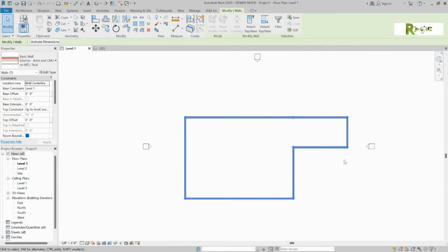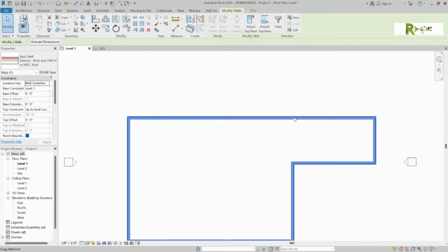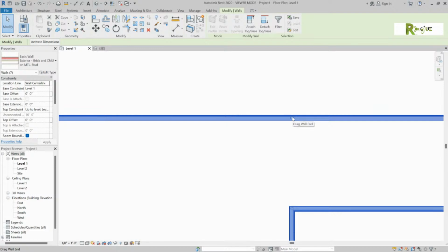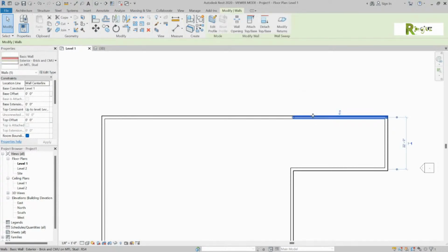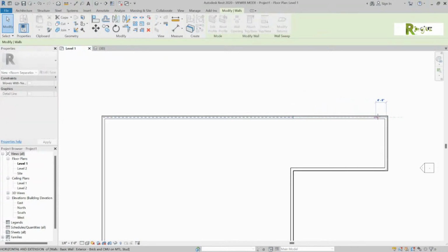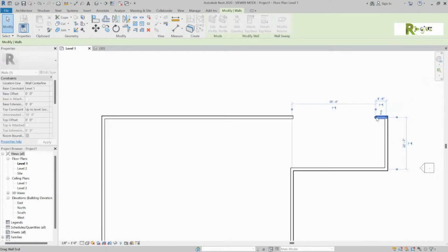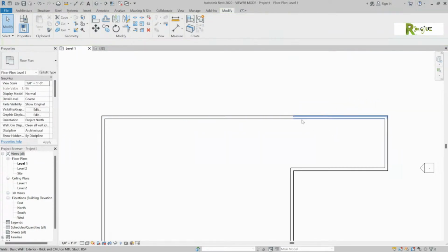Okay? Hey, Brian. Yes. Why does the north wall still have the separation where the other wall was joined in? If he pulled that away, pick one of those walls. Nope. You're picking two walls at the same time. Hit escape. Pick one wall. Pull that dot away. Not that far, just a little bit, just to open up a gap. Now pull it back and tap it back into that wall, and it should turn it into one wall. Nope. It's probably because there are nested sweeps inside that wall. That would be my guess, Eric.